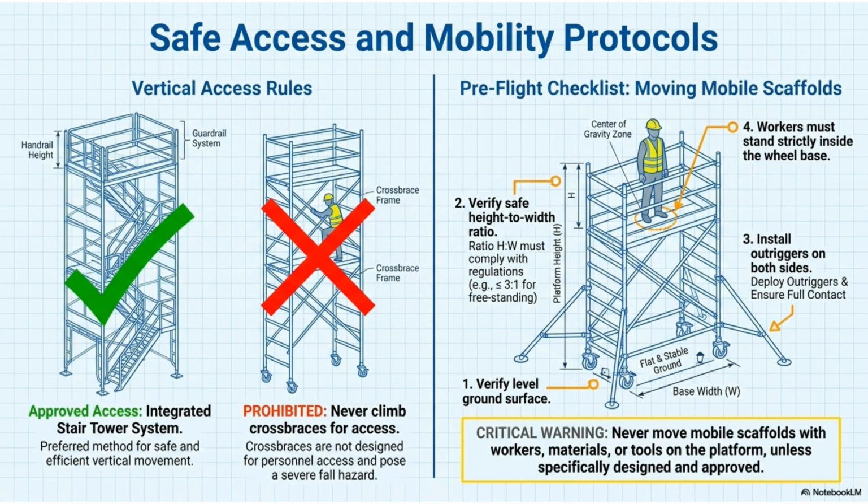Never climb cross braces. For mobile scaffolds, verify the ground surface, install outriggers, and ensure workers stand inside the wheelbase. Never move mobile scaffolds with workers or materials unless specifically approved.